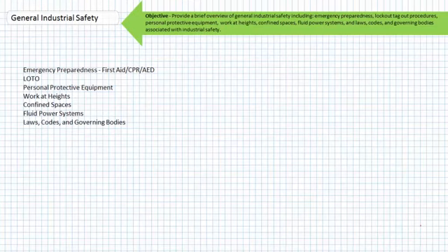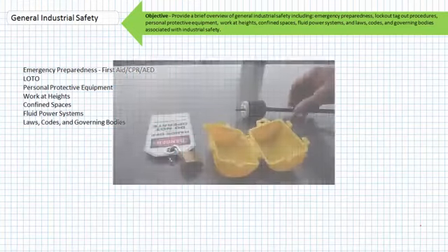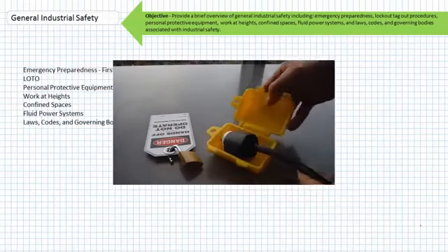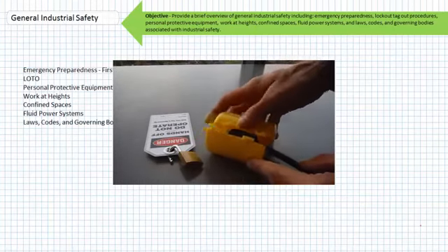Turning off a motor or just unplugging it from a wall doesn't qualify as a lockout, because someone can just walk by and turn it back on or plug it back in. Not exactly the most ideal of circumstances if you're the one doing a shaft alignment on this motor, or if you're the one inside a rotary debarking machine at a lumber mill. Locking it out means exactly that. You are locked out from turning the system back on. This is enabled with locking mechanisms that cover plugs, buttons, or prevent valve handles from being turned. They are then locked into this position by individuals performing maintenance on that system. Here's a lockout device being used on a plug.